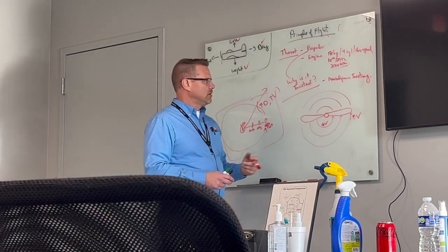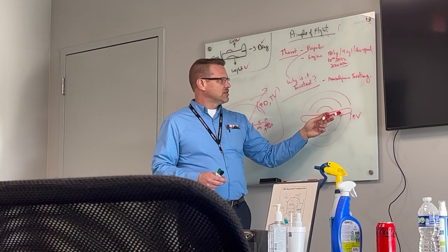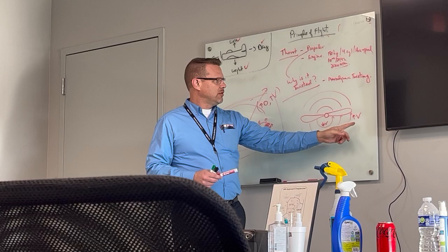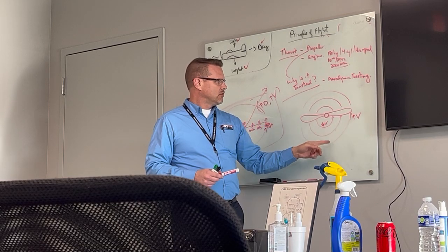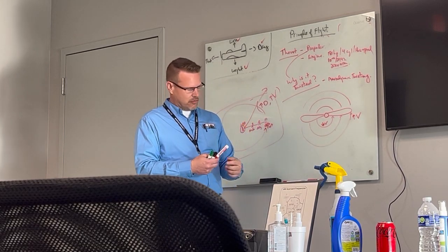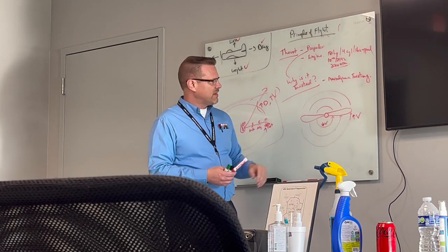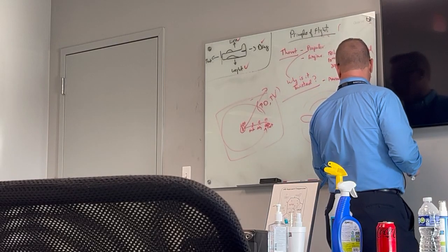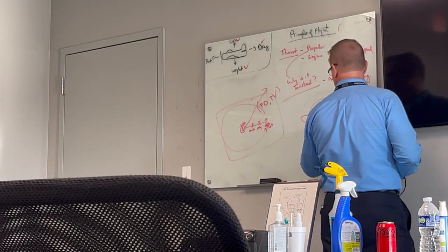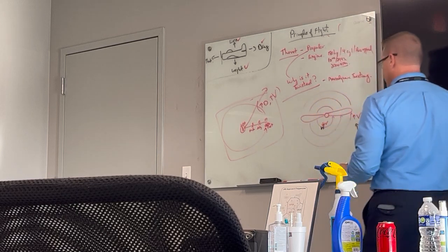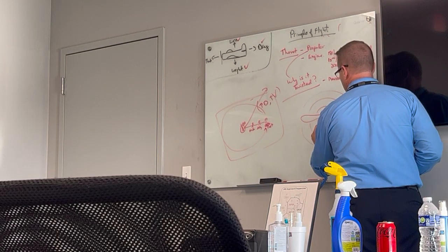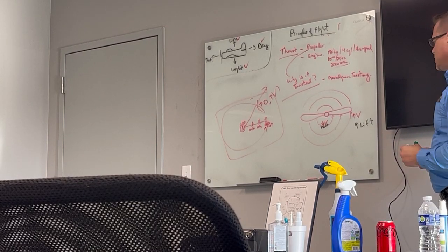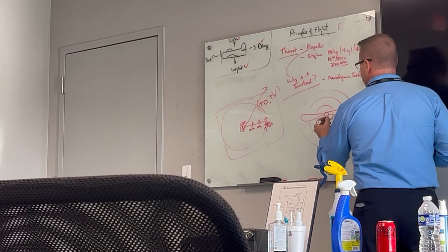What would happen is, we would experience different velocities of relative airflow over the propeller, right? This part of the propeller would be moving very fast through the wind, this portion would be moving very slow. And we know from Bernoulli's principle that the outside would generate a lot of lift, and the inside would generate very little lift.